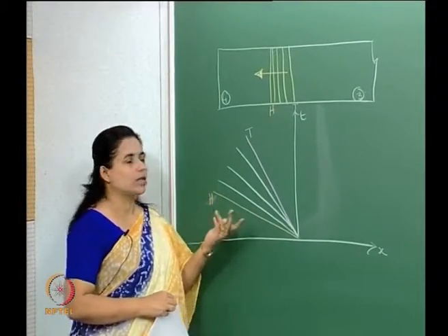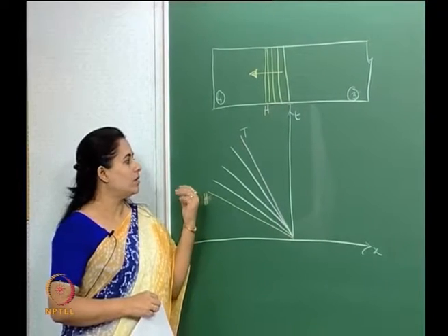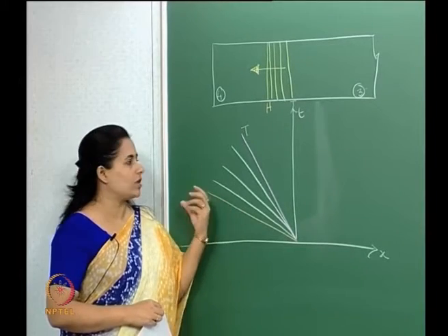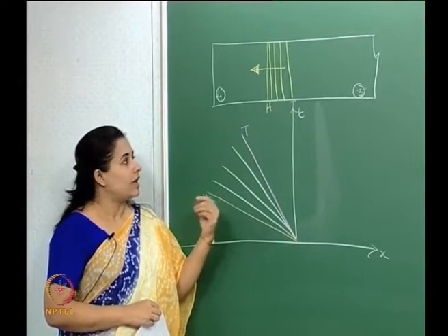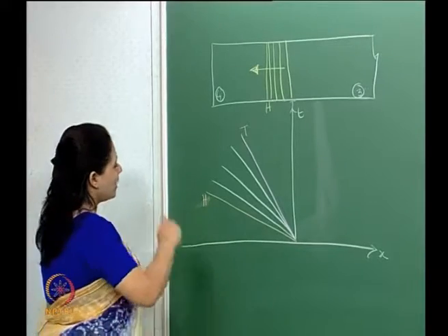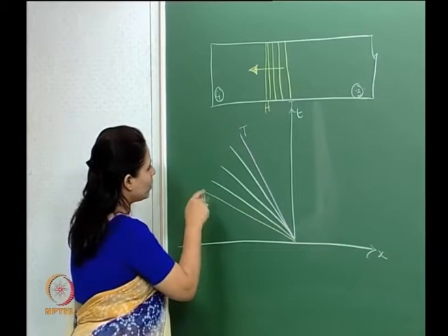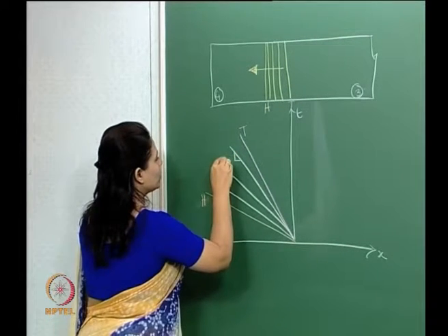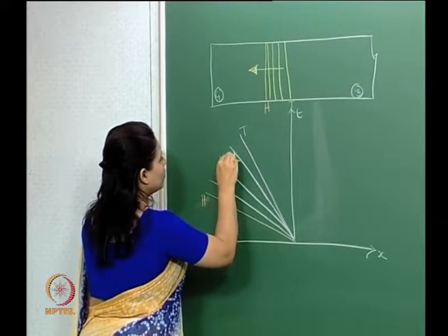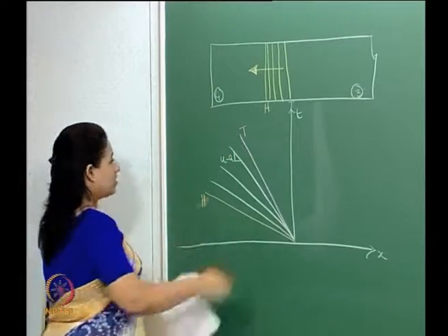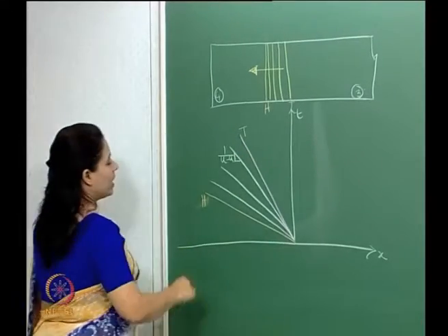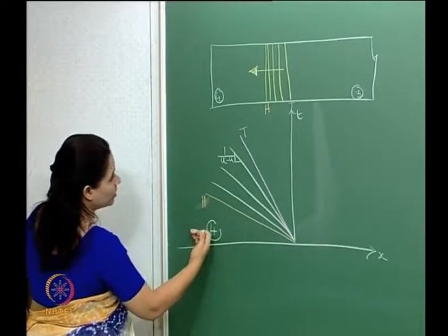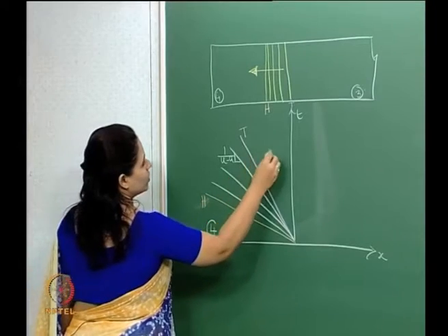These are lines along which the governing equations have their solutions. The solutions to the governing equations lie along these lines, and hence characteristic equations. Now we also said that the slope of this was basically u minus a, sorry, u by a, and the head, as you can see, is moving into region 4, and this is region 3.